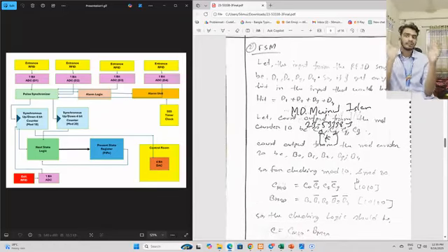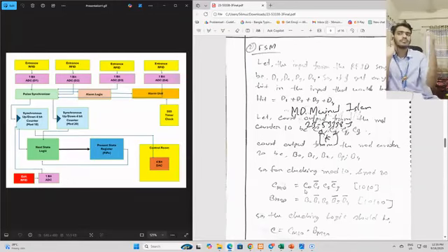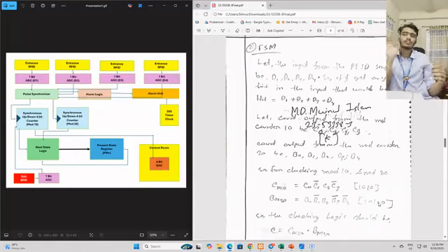So if that's 10, how can we sense that? Remember, if someone is trying to enter, that means we already counted 10, right? If it counted 10, as it's a mod 10 counter, it will be reset, but the system initially gets the hit that the 11th signal is hit. The same goes for this one, that the 21st signal is already hit, as it's already counted. And of course, if it's counted 10 and 20, the counters will go reset.